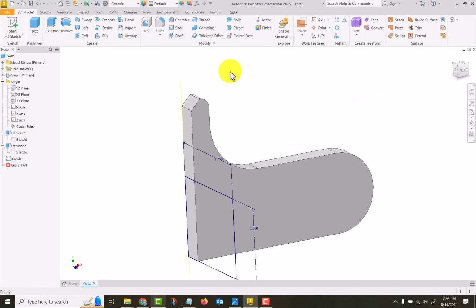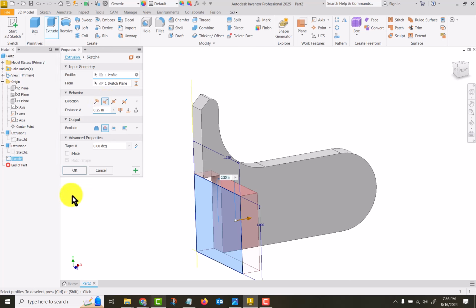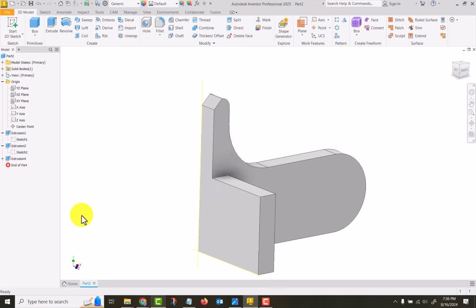And now let's look at it. And we go extrude, and whichever direction I choose to extrude it in will determine what happens. Now you see that little notch out. It's not going to cut the, oh yeah, because it switched to cut. But I want to keep it as extrude, or join, if you will. But I just changed the direction to go back into it. So let's say OK with that.